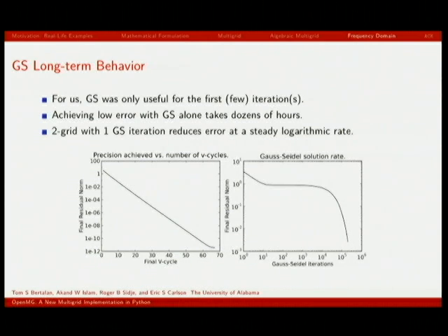And this is compared to our multigrid solver. It does repeated V cycles where it goes high resolution, low resolution, high resolution. And in something like 5 V cycles, it gets what looks like a very similar result to the direct solver, with basically an acceptable solution. And that's a matter of seconds compared to hours and hours for Gauss-Seidel by itself.